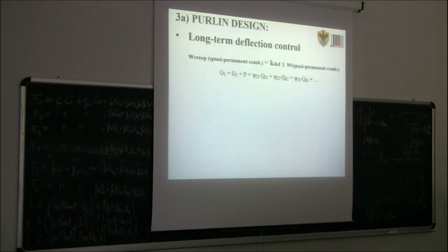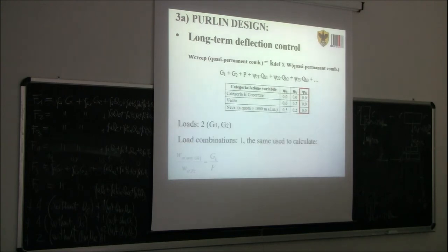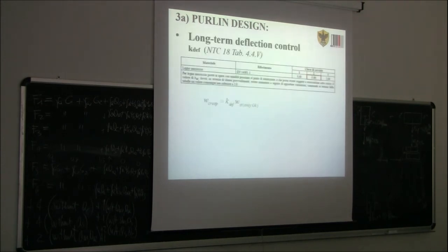We use the same formula to calculate the creep component. So again, we use 8.8 mm, and if we multiply by the creep coefficient, Kdef, we get 7.1. So we now do the sum of all the different components: 23.7.